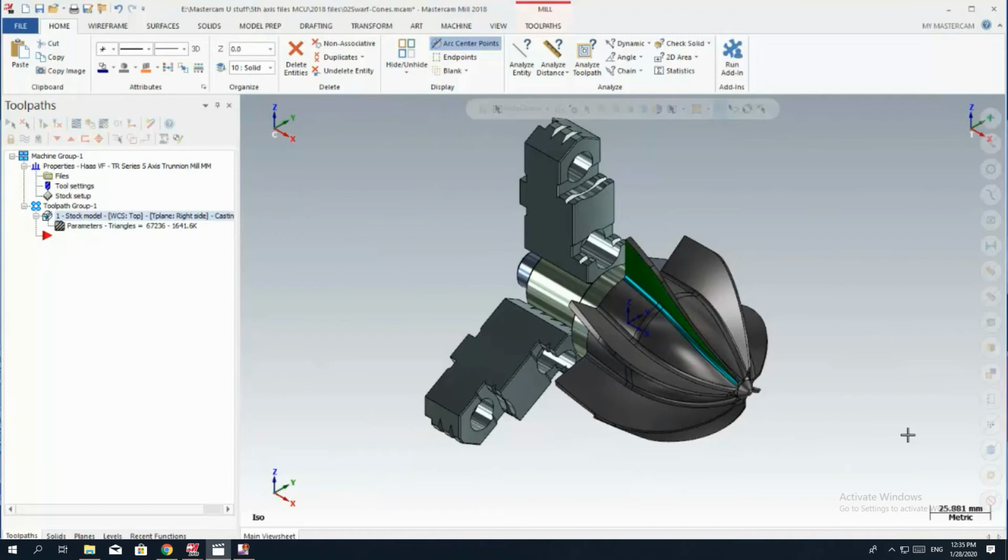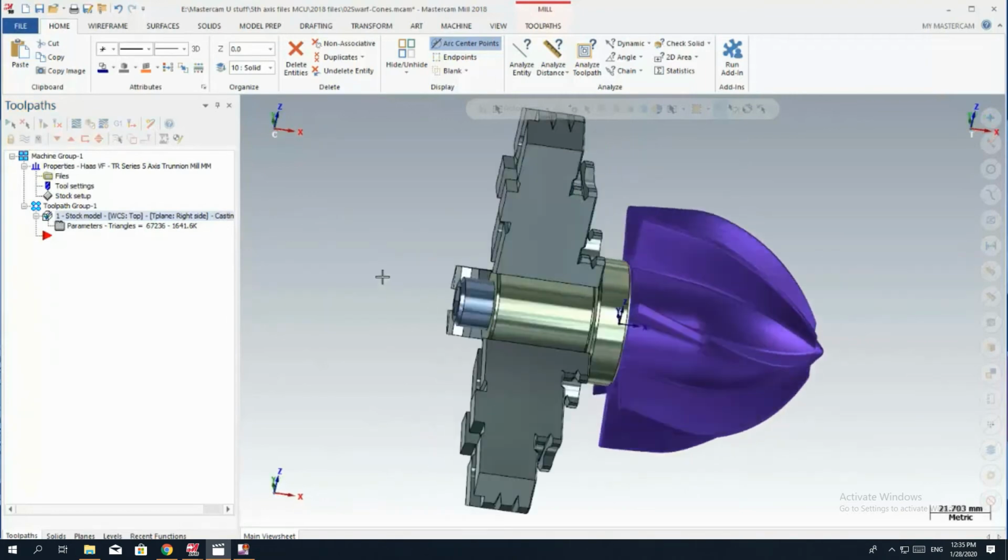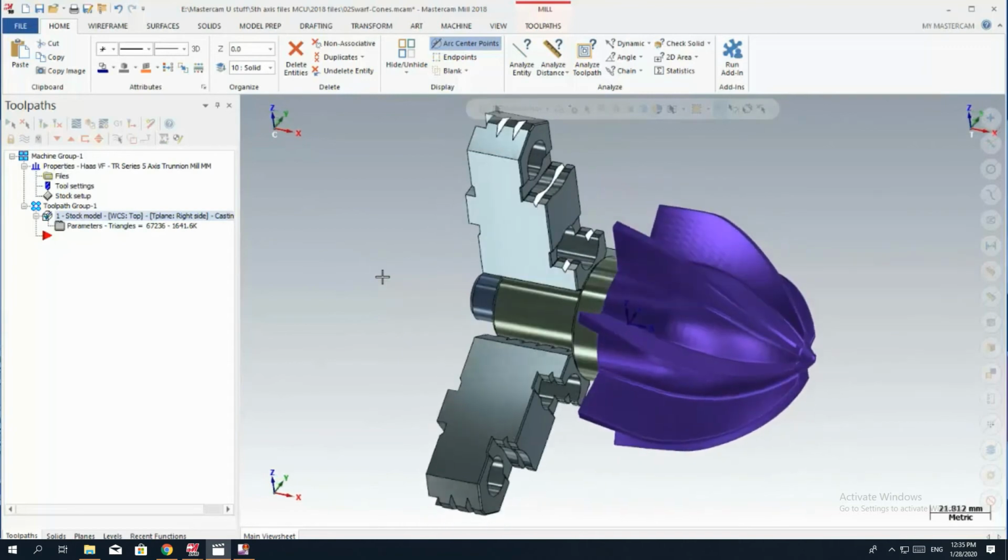Let's start by looking at a few things I have set up for you. First is a stock model with 5mm of stock. As I see this selected here, I'll go ahead and select here, and you can see that we have a stock model, different color with excess of stock on it. Let's go ahead and turn that off. This is set up so when you go to verify, you will see it remove stock as you cut.